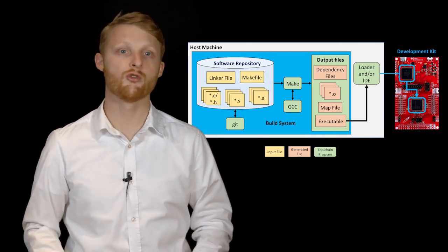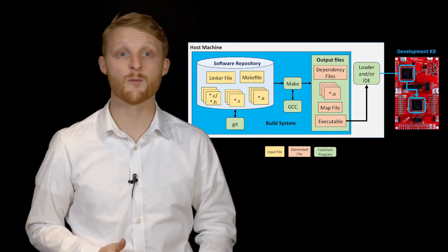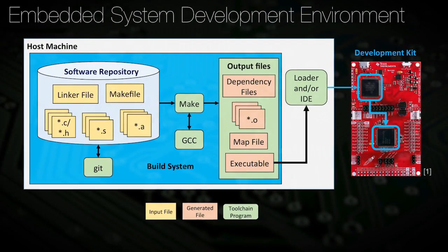This included the host environment, the tools, and the platform. The host machine was where we wrote software, compiled object code, and connected to a target embedded system. In order to use this environment effectively, we had a variety of tools such as version control, the compiler toolchain, and the IDE. The embedded platform included a specific CPU architecture and surrounding components like memories and peripherals.